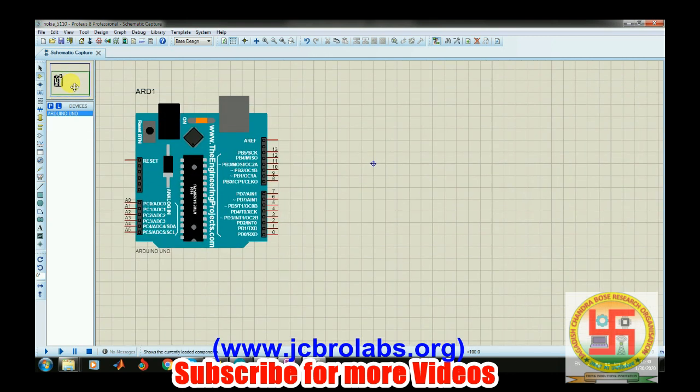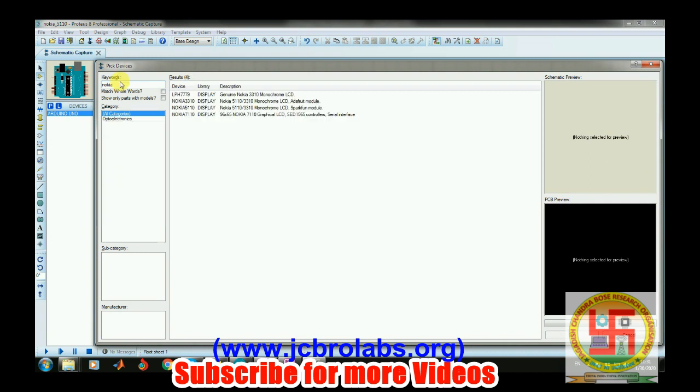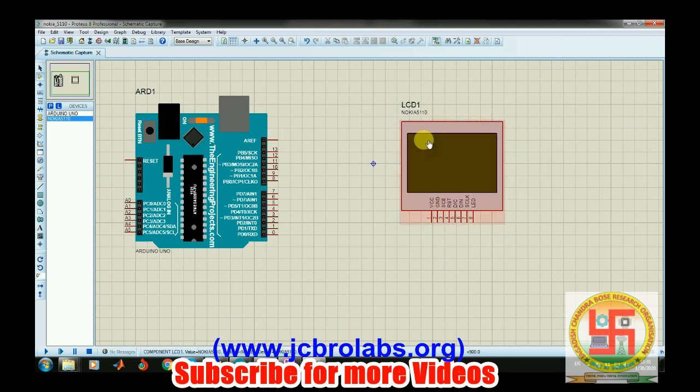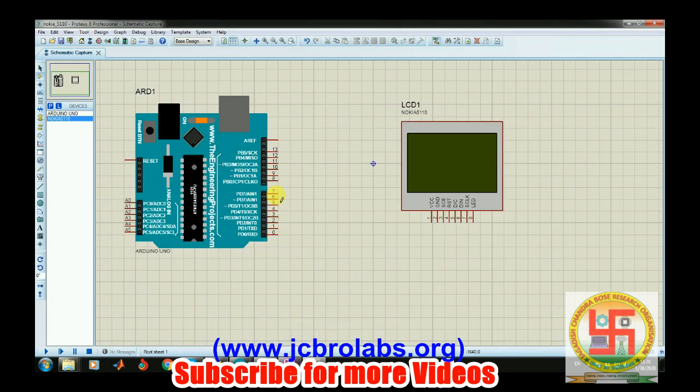Okay, and then let's select this Nokia 5110. Okay, here it is. So we will do the connection as we discussed. Pin number 7 was connected to pin number 3. So pin number 7 is connected to this SCE pin, that is pin number 3. So we'll provide some space, and then pin number 6 is connected to the RST reset.